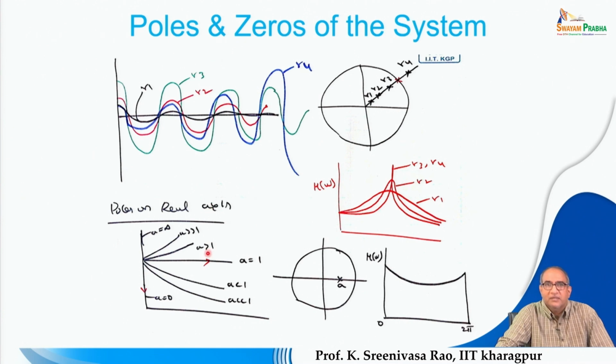And the next thing is that so far we discussed complex conjugate poles, right. Sometimes if you solve the polynomial, it may offer real poles also. Suppose it is a quadratic equation; if you solve it, sometimes you will get real coefficients, and the linear factors will give real poles, the real roots. Real roots means the roots will be on the real axis. The root is indicated by z equals r e power j omega, and if the roots are real, the angular frequency omega is 0. So the roots will be present on this axis,